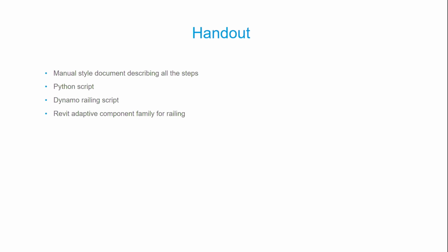So for example, for the steel detailing, connection plates, bolts, we would model that manually depending on the geometry in a separate component, and then use Dynamo to attach it. For example, like the stiffeners, attach it to the geometry following the alignment. So that will be a combination of the two.